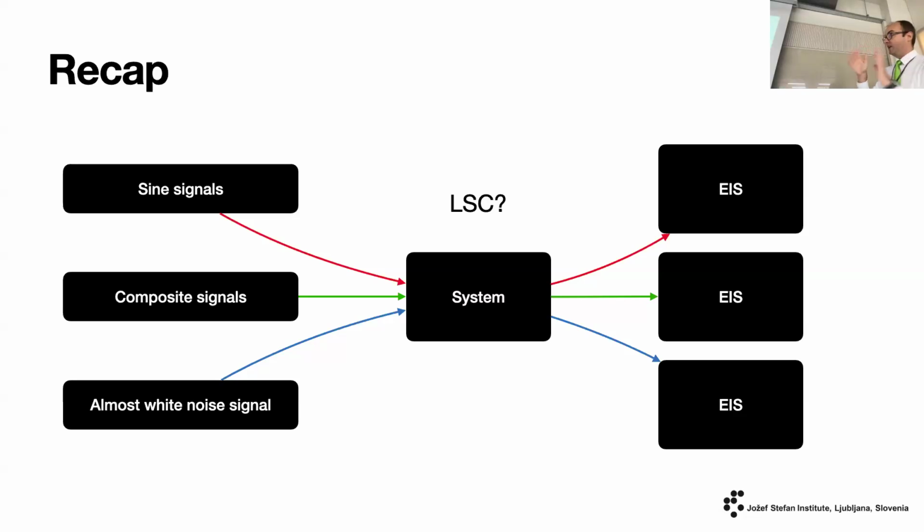So we know that our system is stable. We know that it is causal. The fuel cell cannot look into the future. The only question is, did we do it properly? Are we in a linear stage? So the next thing that I'm going to present today is something called validation of our EIS curves. Are the EIS curves correct?